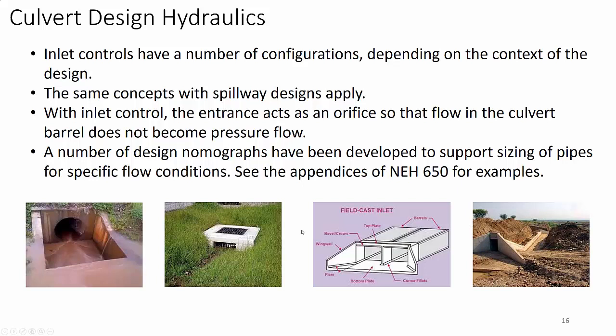A very common set of inlet designs are drop inlets. We saw those with the reservoir drop inlet barrel system for reservoir flow management. We do the same thing with just runoff management under streets and railways. So we have a box drop inlet where the water flows over a crest, and these all act as a weir. It's a broad crested weir all the way around, water flowing down and through.